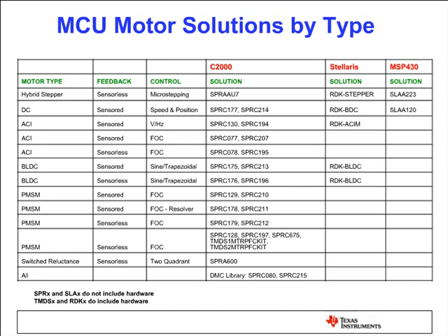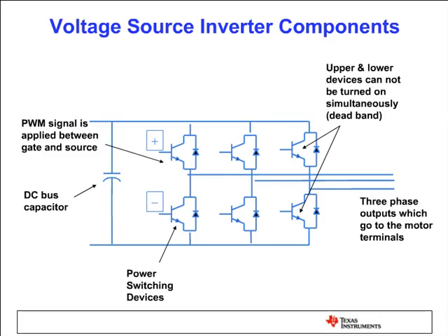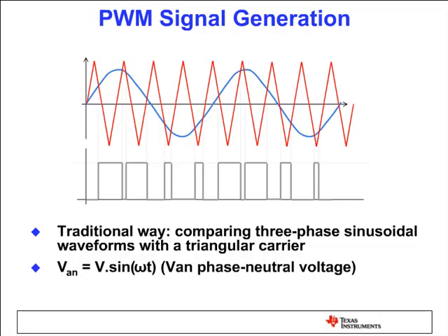I want to skip the PWM part. I had a few slides about the space vector generation. Let me quickly go through this. In order to create a waveform, since our platform is digital, we only have the chance to create pulses, and we can control the duty cycle of the pulses. That's the only possibility we have. So we control the duty cycle of the pulses, and the motor itself behaves like a low pass filter.